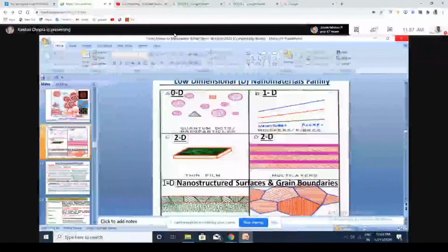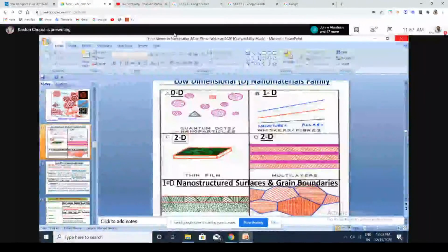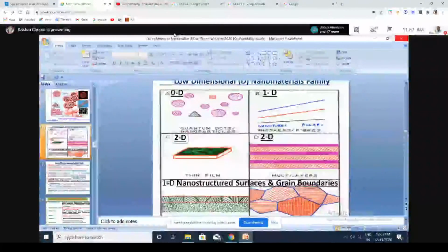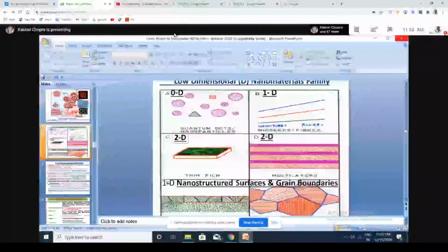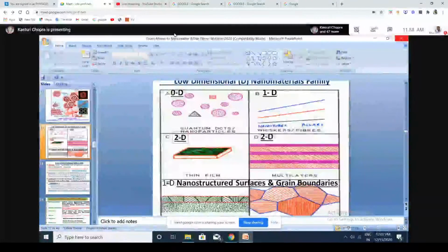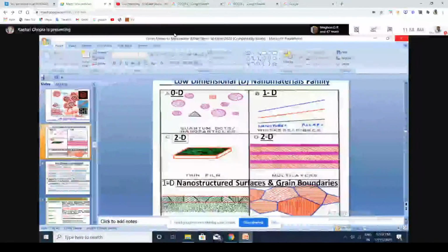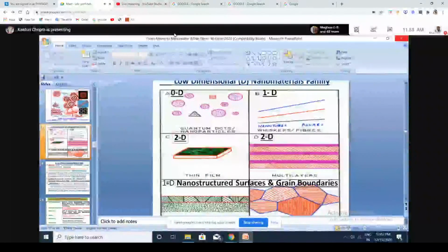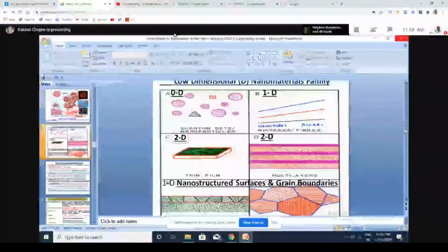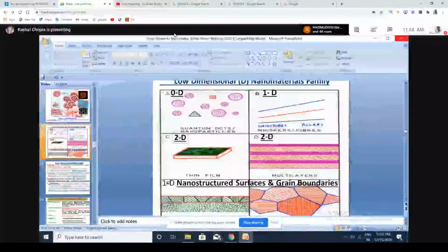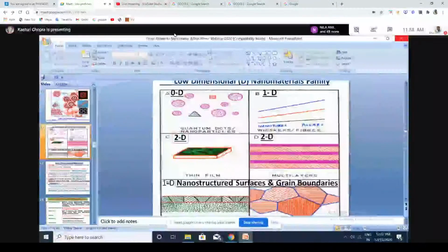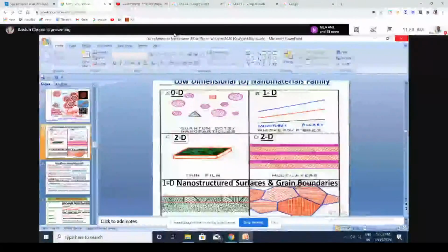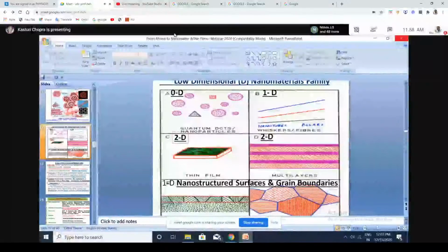So this is interesting, and we have used the property of nanomaterials in making a device. In fact, it has gone to industry, for example, a varistor. We have made a zinc oxide varistor, which depends on the properties of that nanomaterial between grains. In fact, that is the material where pure zinc oxide has a very high resistivity, and you can make a varistor out of that. Similarly, all materials on the surface, like thin films, are nanostructured, and that's why we have a lot of properties of materials, which chemical engineers particularly recognize, and they can be either used or abused if you want to, or they will be mischievous in the properties of many devices that you make.